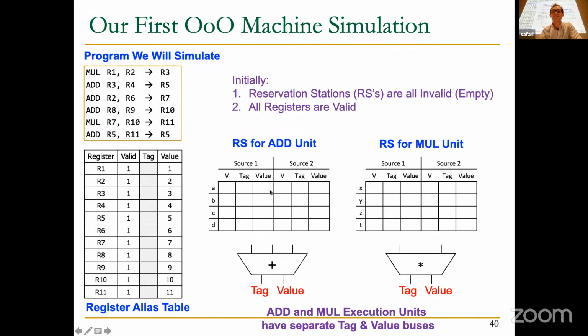So there'll be long buses that are going to go over the entire machine, and you will see this soon. And that's the cost. It's expensive, actually. And if you're doing 2 broadcasts per cycle, you don't have only 1 set of buses like this, you have 2 sets of buses. In existing machines, there are more than 8, 10 functional units. So we do these broadcasts every cycle, 8 or 10 instructions, let's say, potentially. So existing machines are much more complicated than what we're going to simulate. But these exist, basically. You can see how existing machines are so powerful.